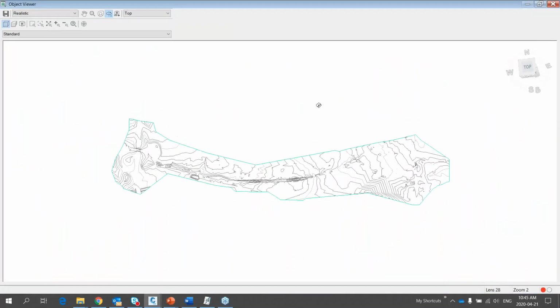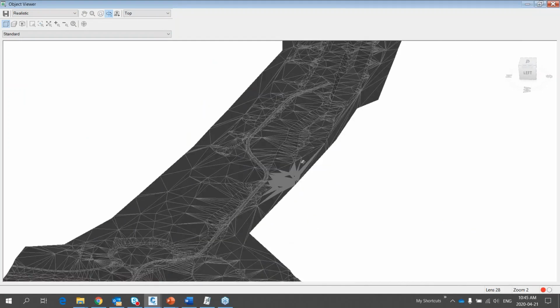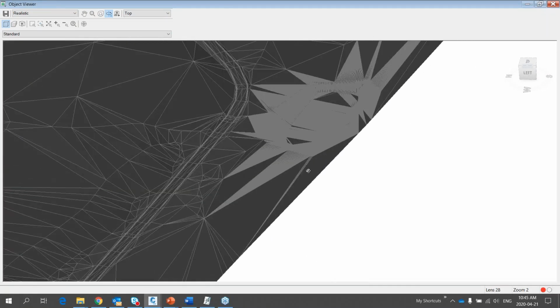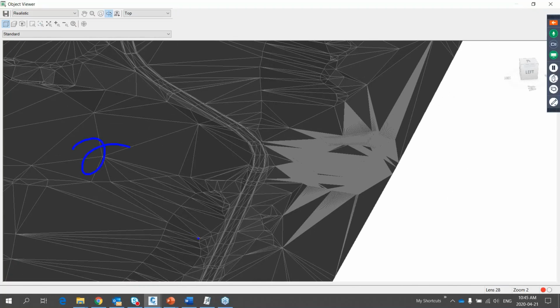You've probably used paste surface before, but maybe you haven't used it in the context of pipes. And there it is. My existing ground is out here someplace. There's my corridor surface. There's my pond. So wherever your pipes come from, wherever they go, it's always just one surface now. And that's the surface that you set for your pipe network.